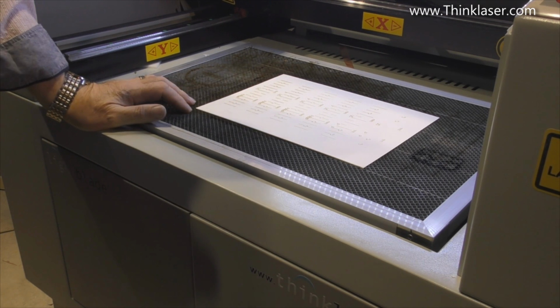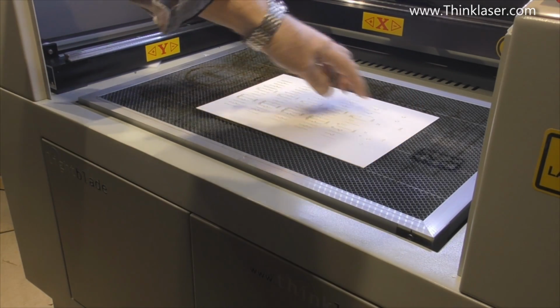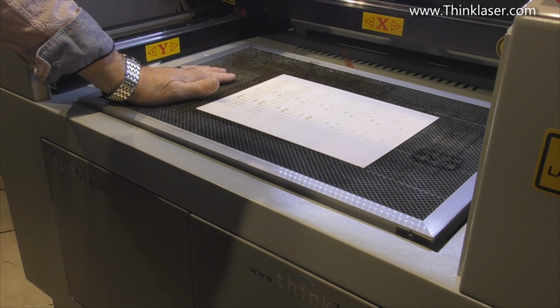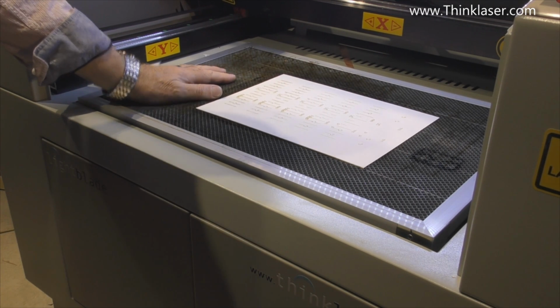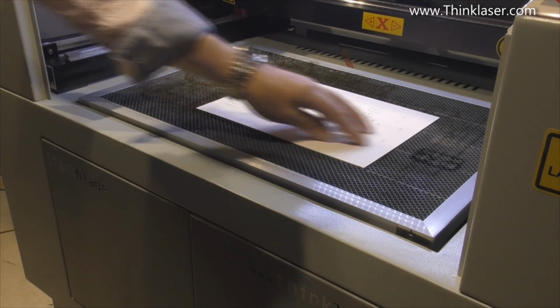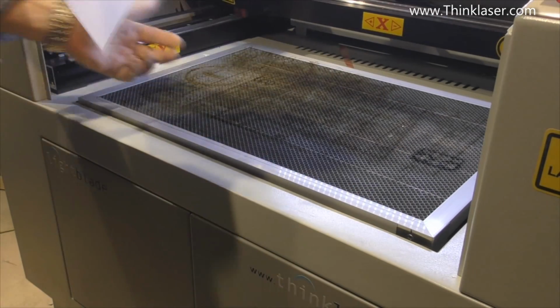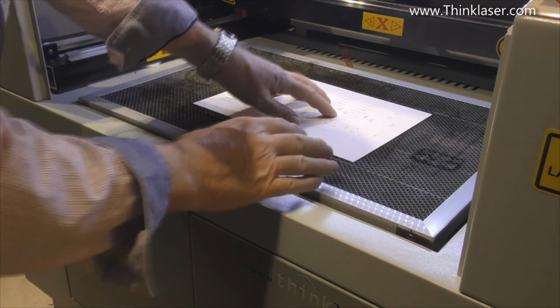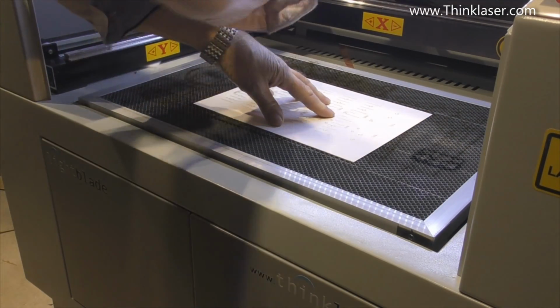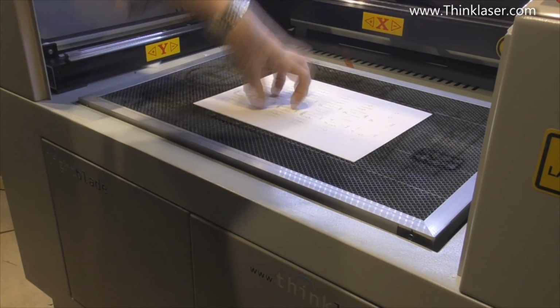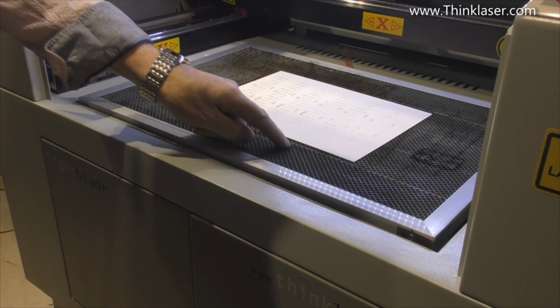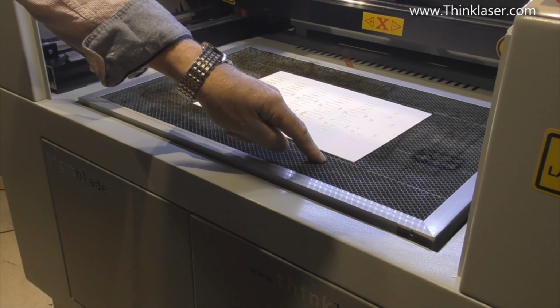Now, you would automatically think, remember how we produced horrible tarry shapes on the flat metal surface? There is absolutely no reason why we won't produce the same tarry shapes on here, because there is no airflow underneath this table. You might immediately think there is because there's honeycomb under there. But hey, all the air is passing down the outside. We've got no air passing down here at all. And so each one of these little cells is a dead cell.